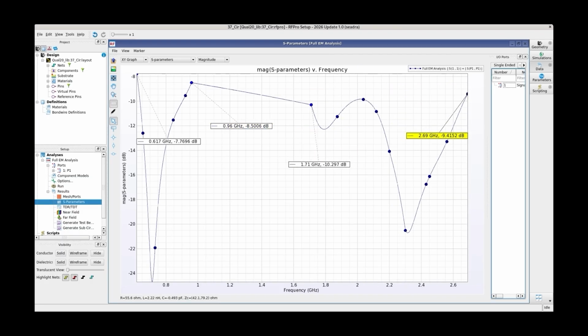The antenna exhibits less than -7.7 dB return loss across the frequency band of interest, which is 617 MHz to 960 MHz, 1.71 GHz to 2.2 GHz, and 2.3 GHz to 2.69 GHz, which indicates the antenna meets the specification we shared in a table before.